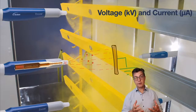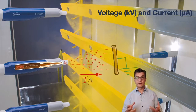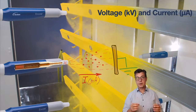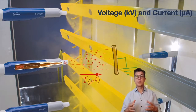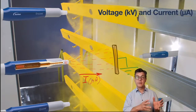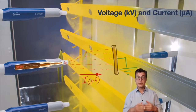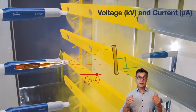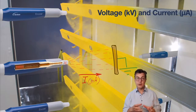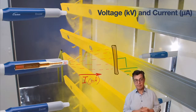Once we've applied sufficient voltage to the tip of the gun and created a sufficiently strong electric field for the development of the corona discharge, the space between the gun and the part is populated with millions of charge carriers. And it's the flow of these charges from point A to point B, which is the current. So the current is the only direct measure of how much charge is created and passed from the gun to the product. So what about the kV?